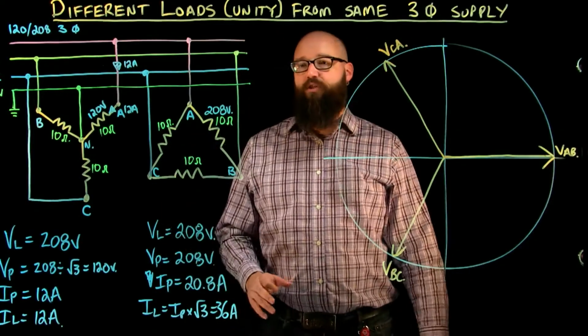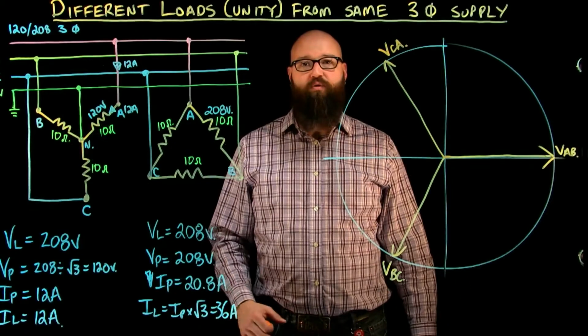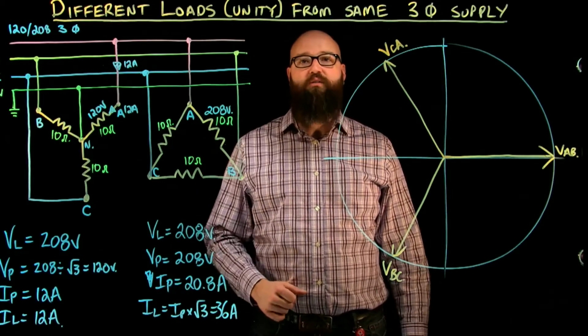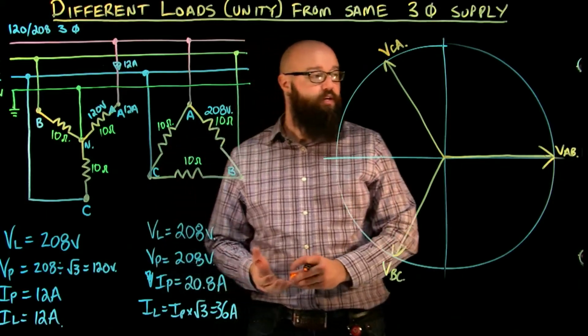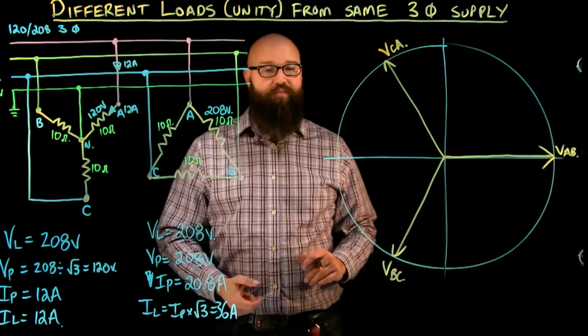Now I say line voltages because in a Y system it is our line voltage. It's also our line voltage in a delta system, however it is also the phase voltage in a delta system. So that's why we want to use it as a reference.